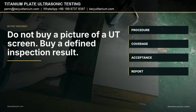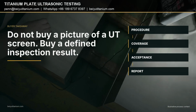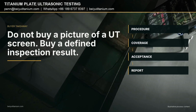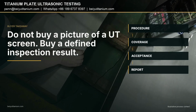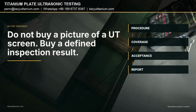The footage in this guide is workshop process context. It is not presented as proof of the exact heat, lot, or order in a quotation. For an RFQ, define the plate, method, coverage, calibration basis, acceptance criteria, reporting, and traceability before inspection begins. Do not buy a picture of a UT screen. Buy a defined inspection result.